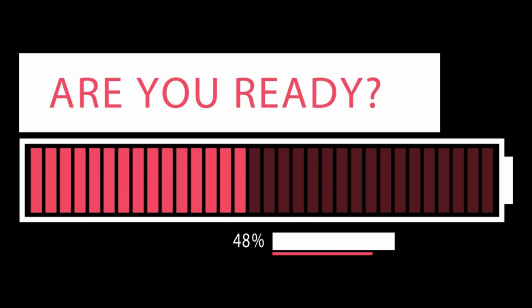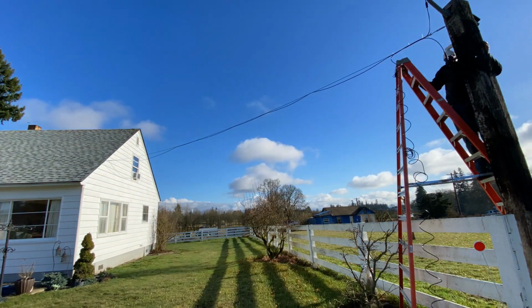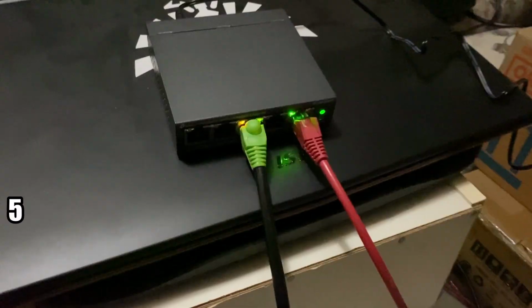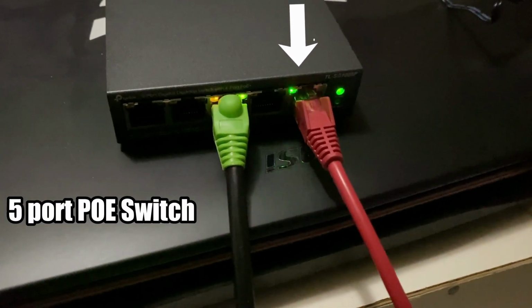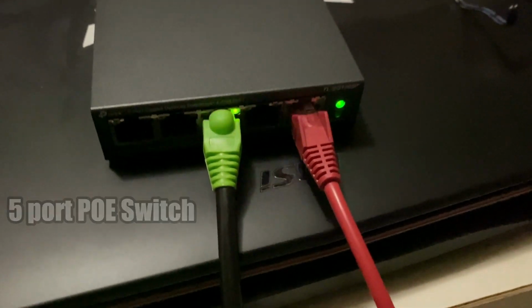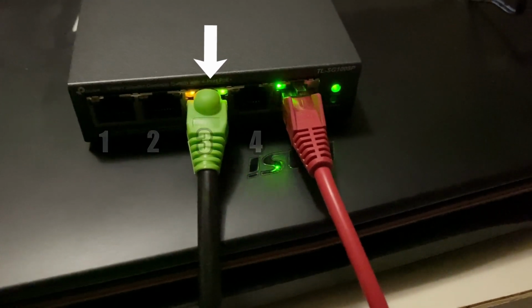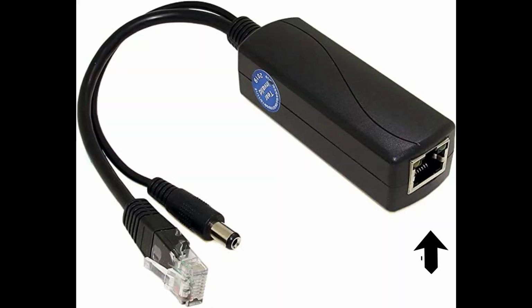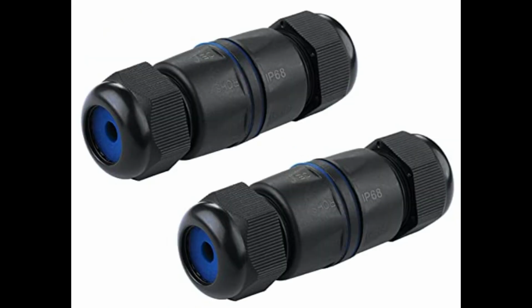Let's get started. If you're planning to remote the camera and need to send power to the camera through the Cat6 cable, then use a small Cat6 cable and plug the 5-port PoE switch on port 5 into your router. Plug the 100-foot Cat6 cable into port 1 through 4 of the PoE switch. Then plug the other end of the 100-foot Cat6 cable into the splitter Y adapter that came with your camera. Use the waterproof connectors that came with the camera to make the Cat6 connections waterproof.